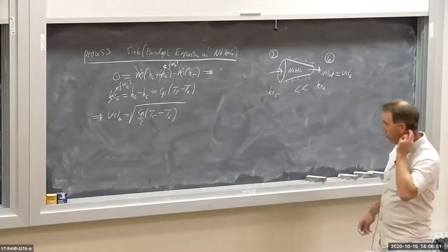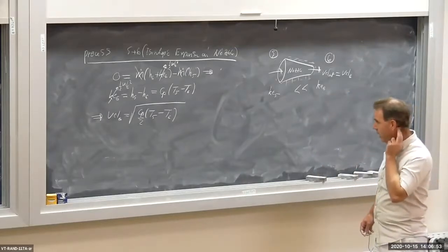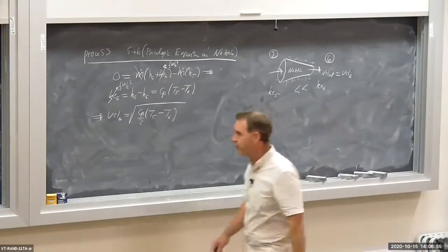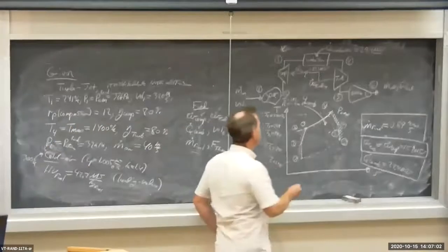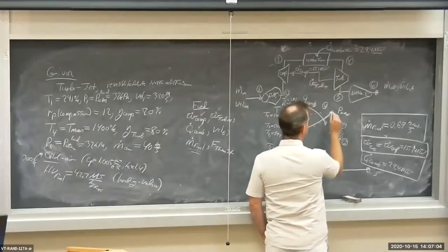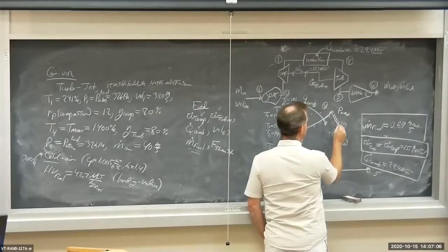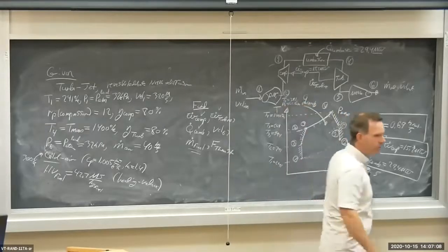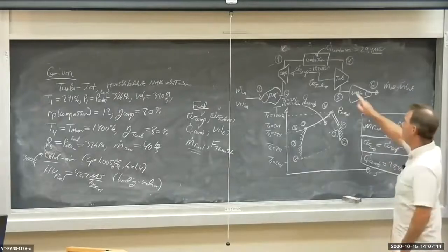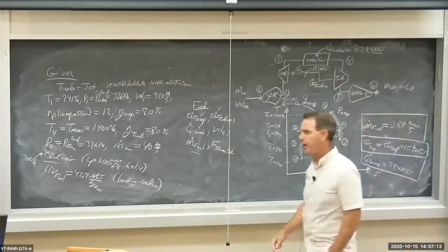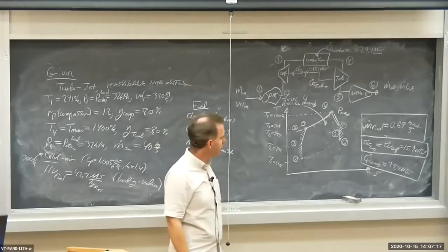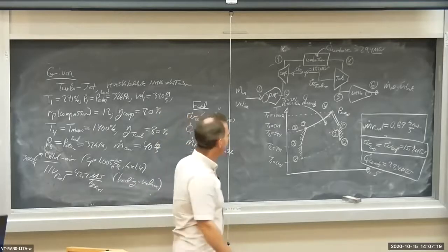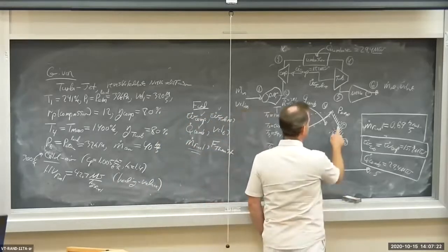I don't think I'm going to go through too many of the details on how we get T5 here. Suffice to say, I can apply the energy balance from 4 to 5, noting the isentropic efficiency of the turbine. So 4 to 5 is the turbine expansion process. I can apply isentropic efficiency to the energy balance, and I can get an outlet temperature, T5.